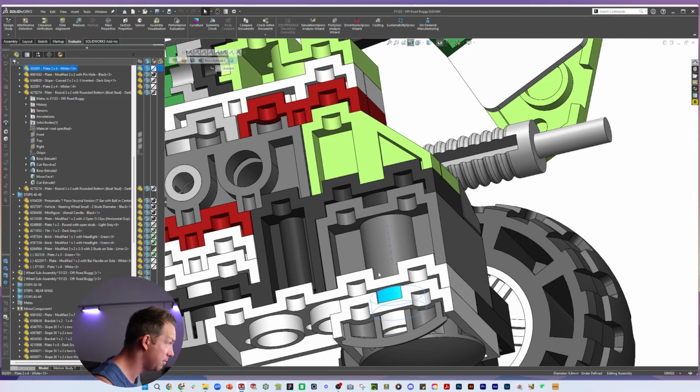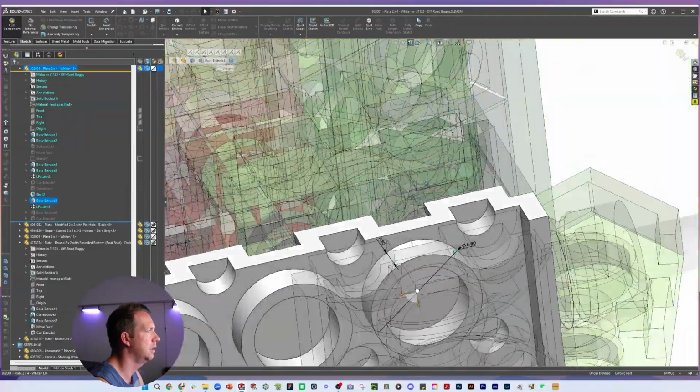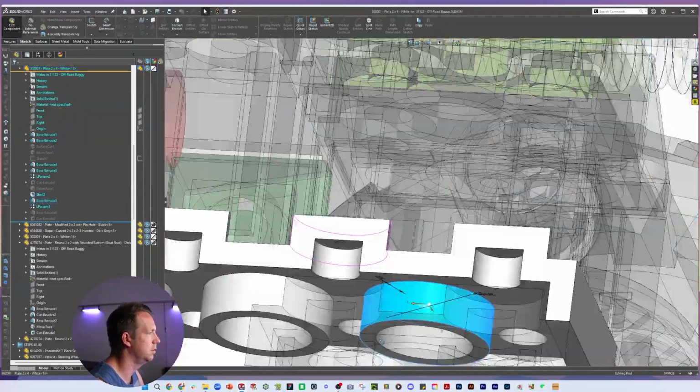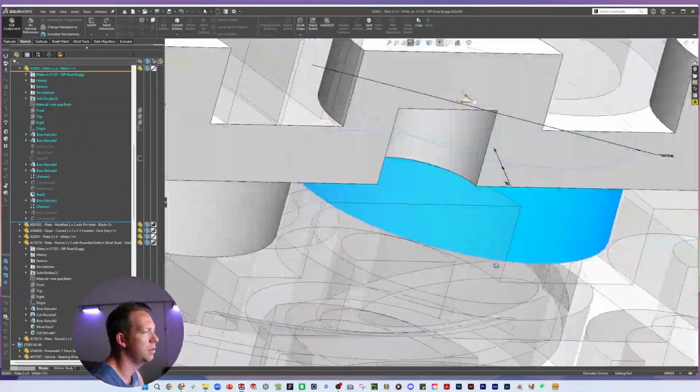So if I was to measure one of those elements again, I do have digital calipers coming. I just need a battery. Measure one of those again, and I'd have to say it's closer to 6.4. So I'm going to edit that, click on that one, change to 6.4. Does it still have interference? No. See, it clears it.